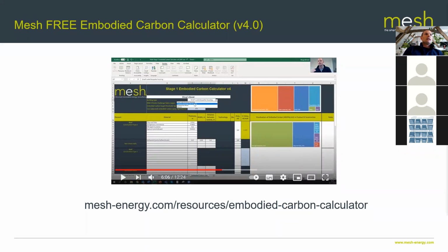So certainly at the early stages of design, you just need to make sure you're heading in the right direction. You can always tweak the values up and down, but you need to make sure that fundamentally you can achieve values with the kind of materials and the kind of wall thicknesses, roof thicknesses and floor thicknesses that are acceptable. But that's a fair point, Sophia.